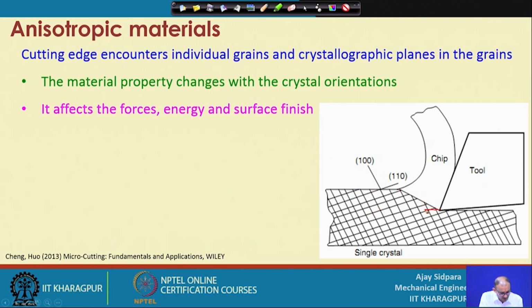So, when it is coming like this in this direction, now you can see that this grain has to be cut out, this grain also, you are getting the point. So, it is very easy to cut in this direction, but many times this will not happen. So, you have to cut this grain; again, the orientation of this grain plays an important role that we have seen. And then if you continue in this direction, many times you can come across this grain boundary, but many times you may not come across this also.